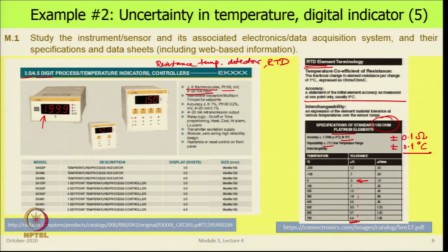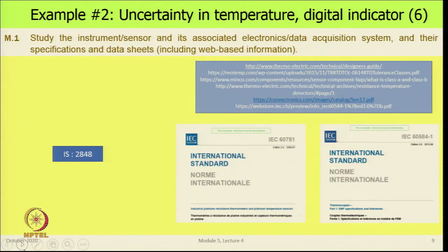And then again it is not good. So, if you want to use a T type thermocouple, this is not suitable, we cannot use it. But let us see what else it tells us. Accuracy is 1%, for RTD it is 0.2% and for current it is 0.1%. And there are the various models that are there. So, here is a slightly different type of device, but it is not good enough for a T type thermocouple. Now, let us look at some standards.